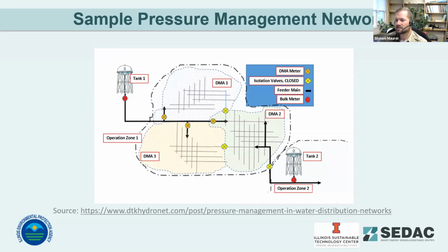So, municipalities that have implemented this kind of work have reduced water losses by about 30% or so for well-managed district systems. But it's particularly useful for areas with significant topographic variation. But that's not the only application. For larger distribution networks that have varying demands in different zones, pressure can swing from zone to zone of that control area. So these management systems can help redirect flow where it's needed, can help maintain that pressure more evenly across the whole system, and manage that water demand so that it has less impact on the operations at the plant itself, and tries to even things out.